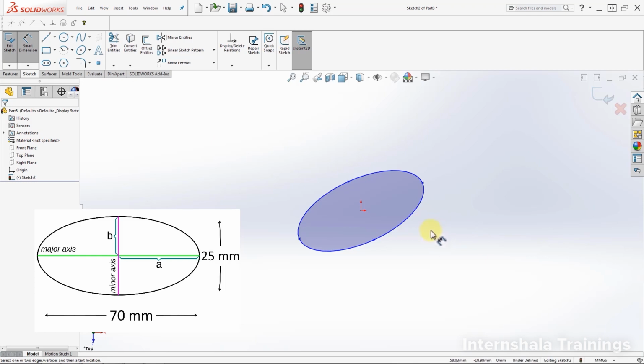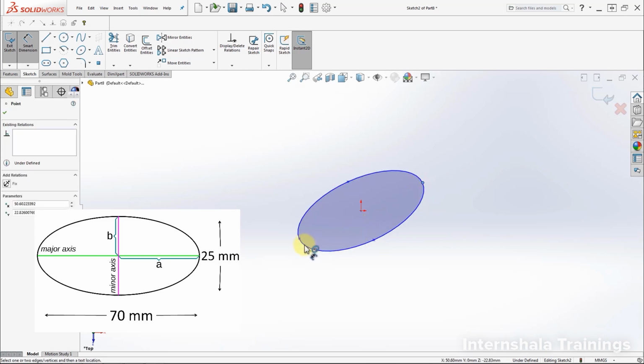Whenever we see points, we can use those to determine a dimension between the 2 points. So let's go ahead and click on this point here, and then click on this point here, and then we get a dimension measurement. Now notice that if I move the mouse around, we get the dimension from a different view.